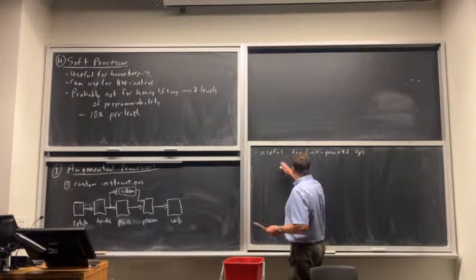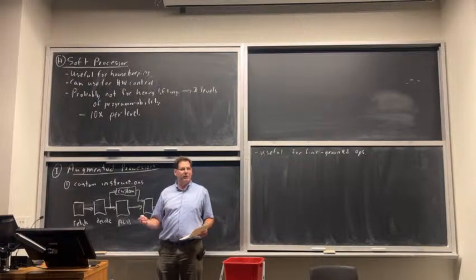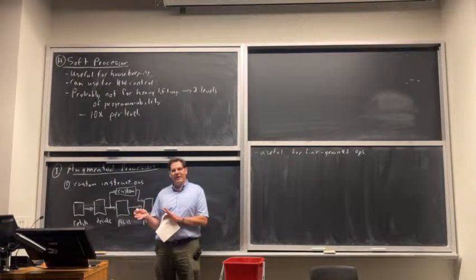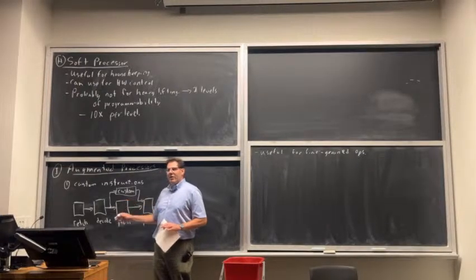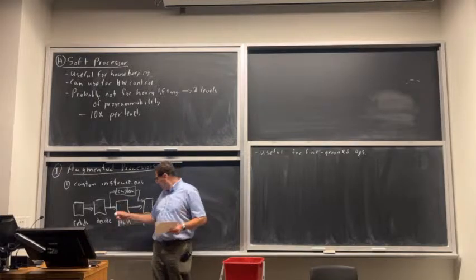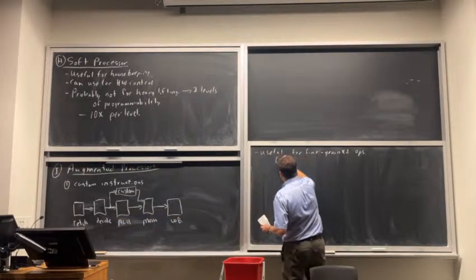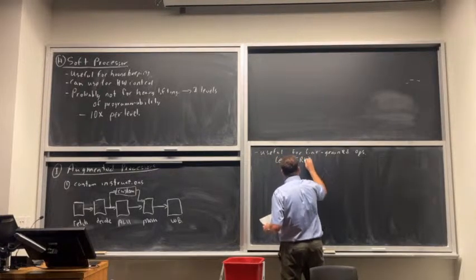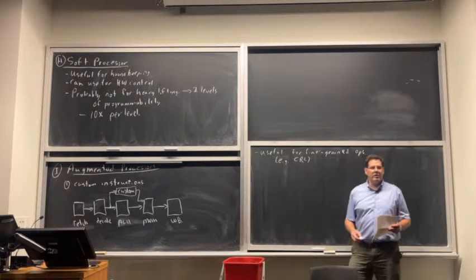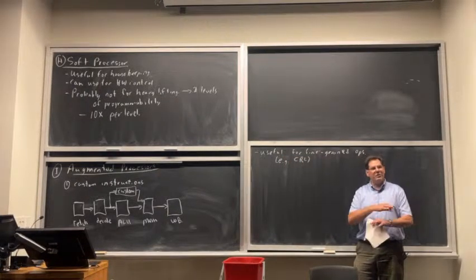So it means it's mostly useful for things that behave a lot like regular instructions, where they don't need that much input data, like add or multiply, and they don't take that long. But they can't be add or multiply because we can already do that here. So an example where this has been quite useful is things like cyclic redundancy checks. You use cyclic redundancy checks in encryption and in parity checks. They're basically a whole bunch of shifts and XORs.